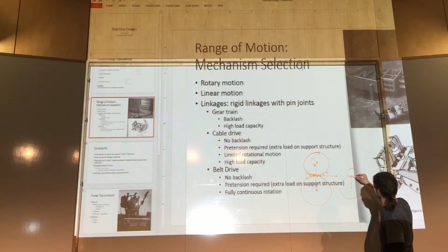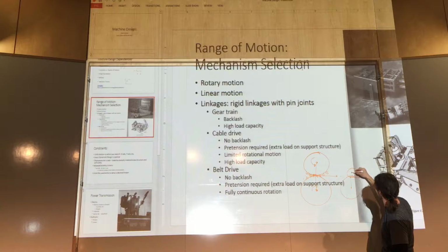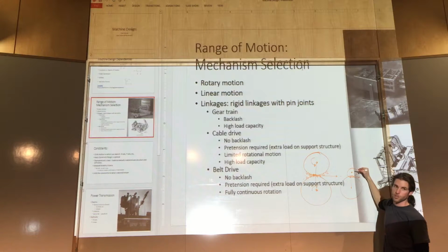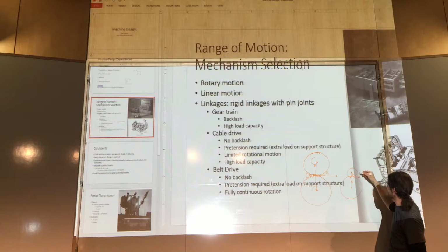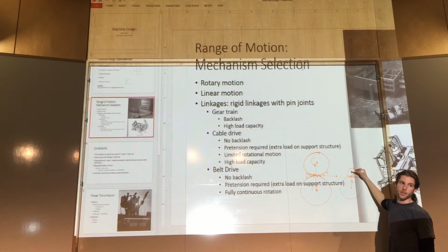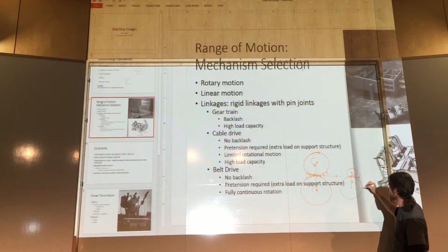The gear ratio ends up just being the difference in radius between these guys, R1 and R2, or the ratio between the two of them. And so as this guy's rotating around, this guy will end up spinning a lot faster because he has to go around a whole bunch more times in order to make up the same distance around the circumference here.